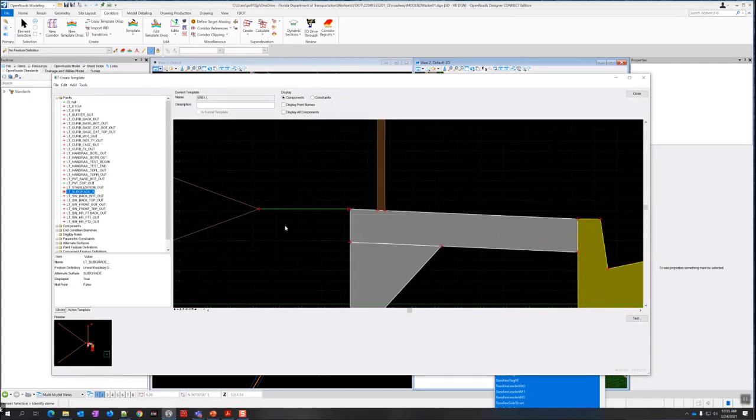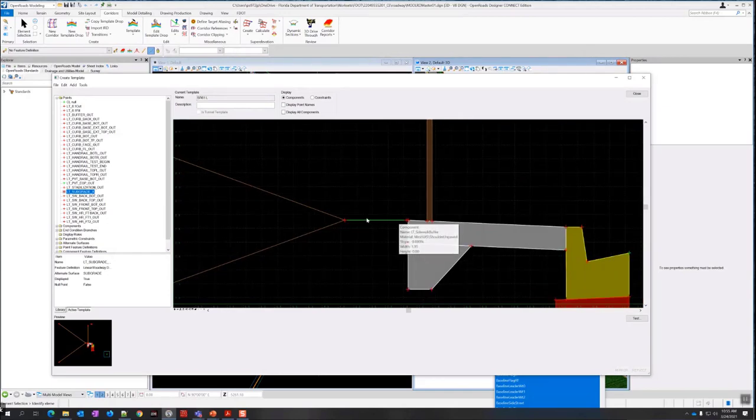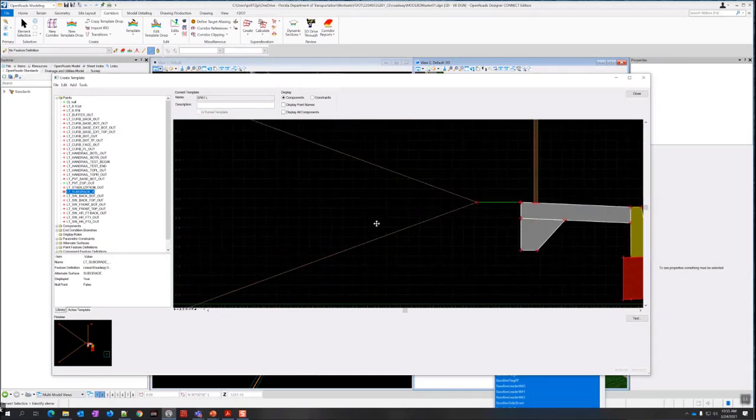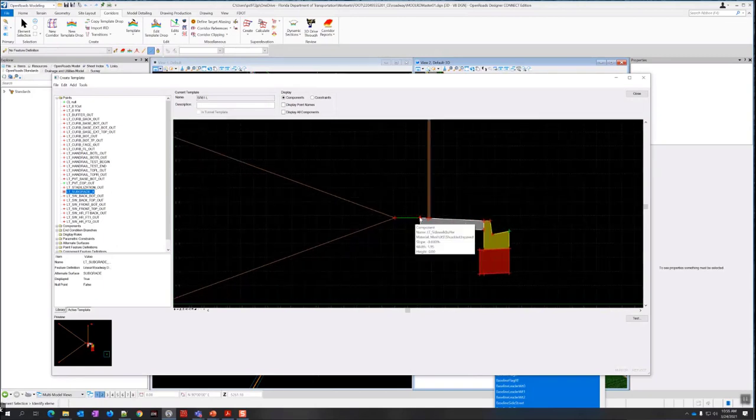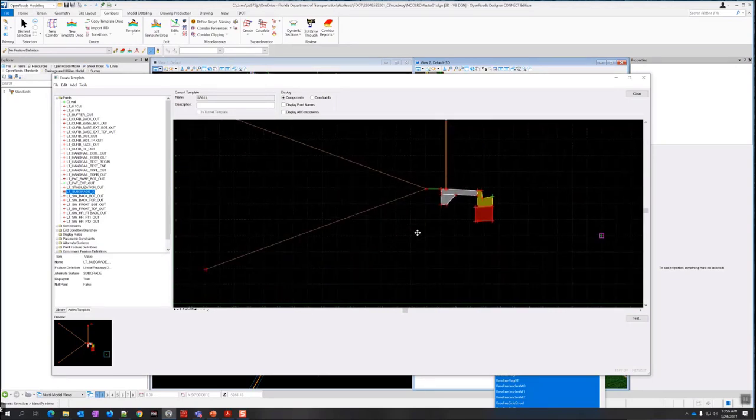And then the subgrade, so these slopes are proposed top, but these also need to be on the proposed subgrade. The idea with the subgrade surface is we can use it to run our earthwork. In fact, we'll do it in the next chapter when we do earthwork. We'll do a surface-to-surface comparison with these surfaces that we created.